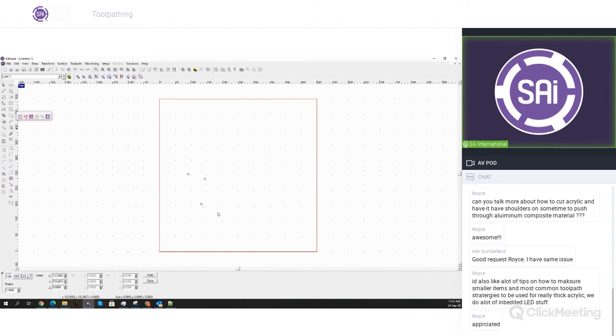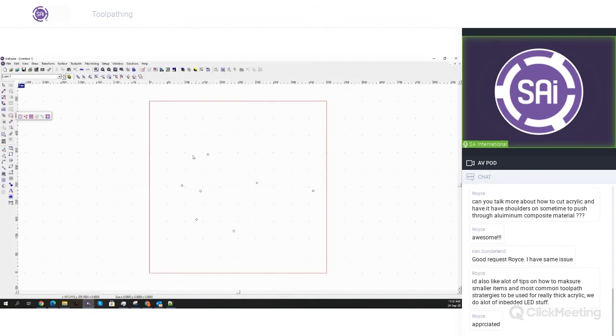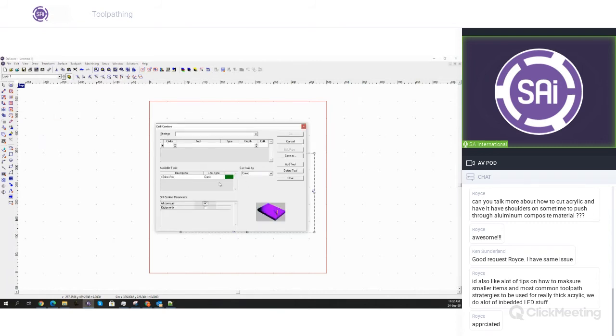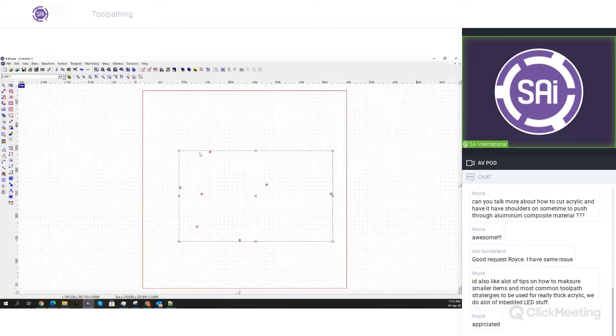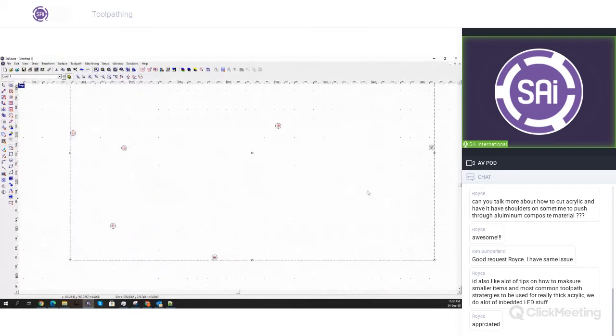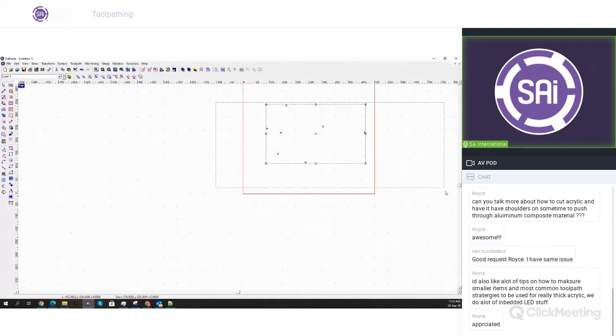What that'll do is, if you have multiple objects on your plate, you can drill the center of objects. And then here, let's go into drilling. Drill 3s. Here we can choose all contours or just drill circles only. In this case, it doesn't really matter. And as you can see, it'll put drill points in every contour right in the center.